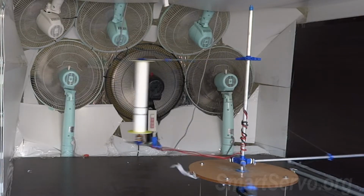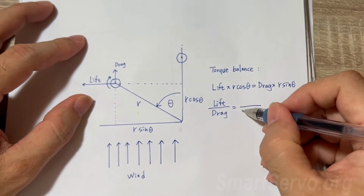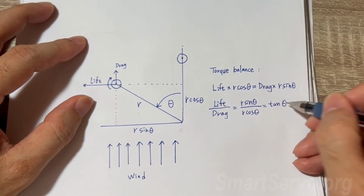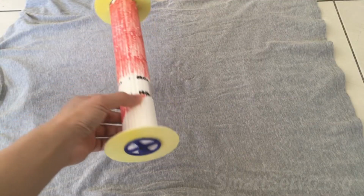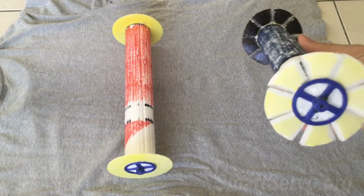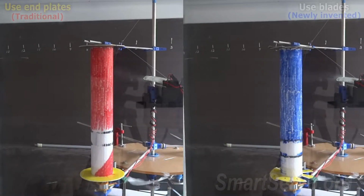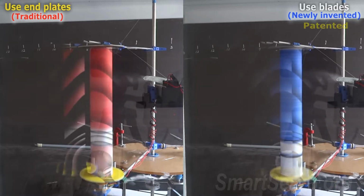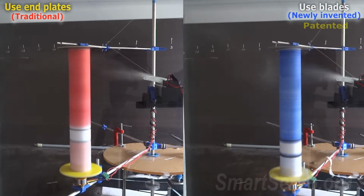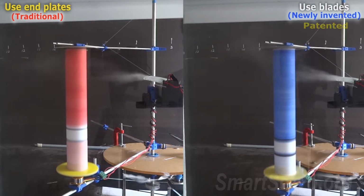When the rotor rotates in the wind tunnel, the lift-to-drag ratio is equal to the tangent of the deflection angle, theta. Therefore, the larger the deflection angle, the larger the lift-to-drag ratio. The red rotor uses traditional end plates, the blue rotor uses blades. The smoke blower is 1/4 below the upper end of the rotor. The wind speed is about 2 meters per second, and the rotor rotates at 3,800 RPM.